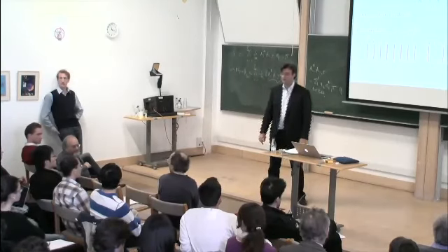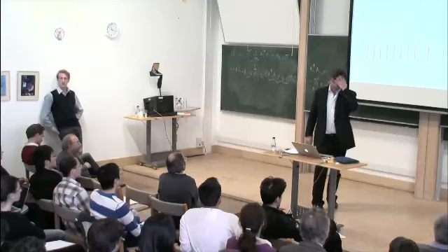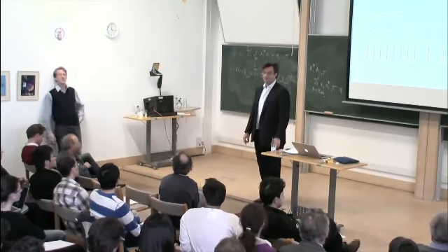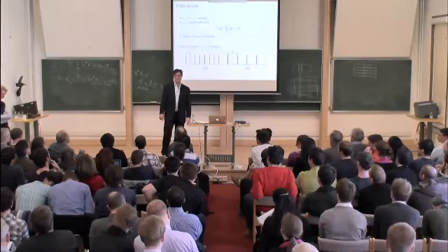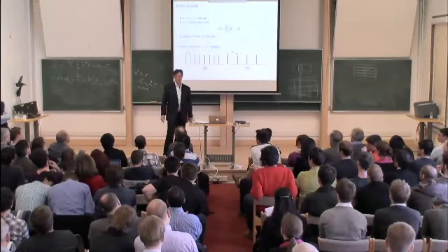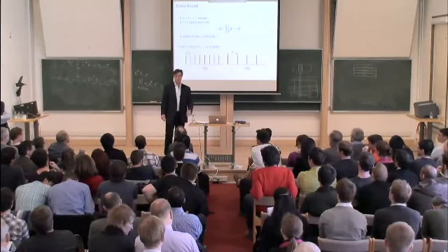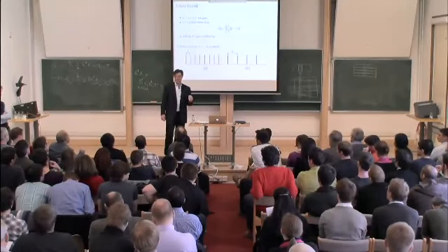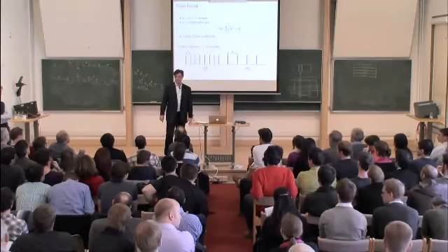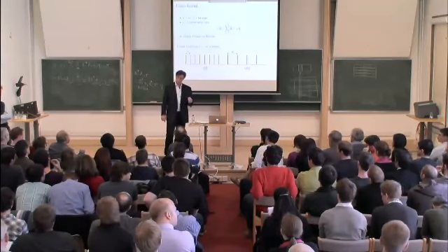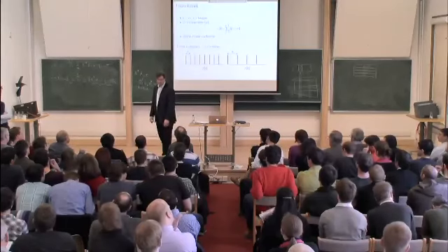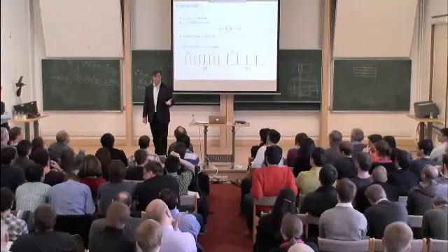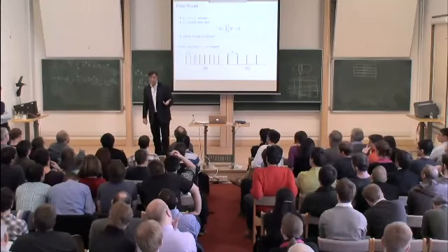Do people use this in practice? I mean, you mentioned that these things are going to hardware implementation, and there you can save a lot. But the beautiful thing about hardware implementation is that I can actually randomize my sensing device. That's why I think it's an exciting field. I can go to an engineer and say, why don't you load in this buffer a random sequence of plus and minus 1 so that we're actually measuring random samples of the signal. I can tweak an ADC, an analog to digital converter, so that instead of sampling uniformly in time, it samples non-uniformly in time at random locations. I can do this. I just mess up the clock.